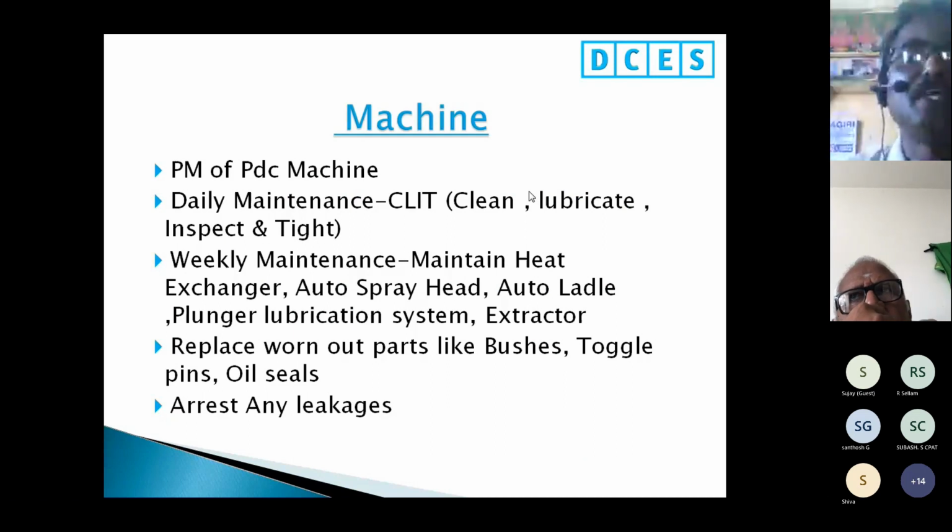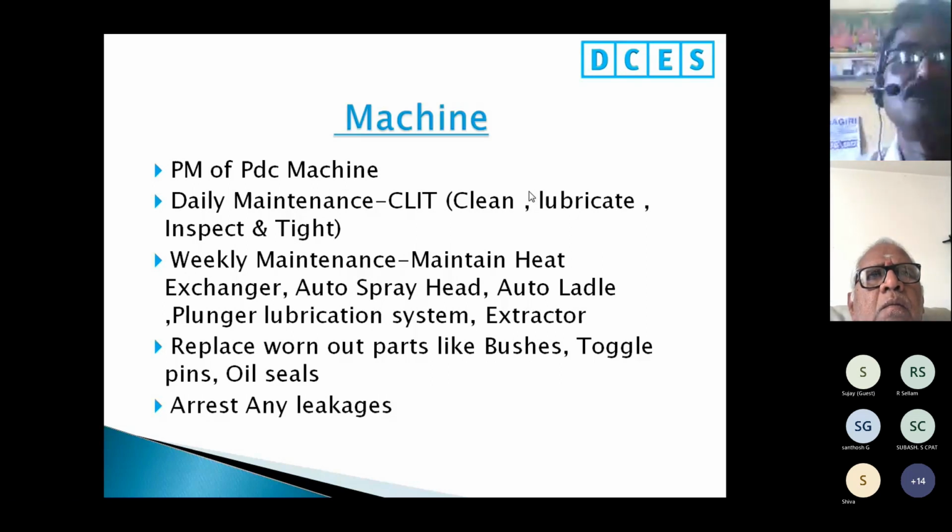Weekly maintenance: maintain the heat exchanger, auto spray head, auto ladle, plunger lubricant system and extractor in good condition. This should happen during the weekends. Give a little effort, assign a few people to this assignment during the weekend. You will not have any problem during production.